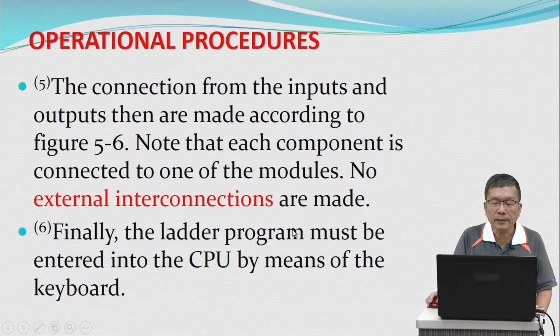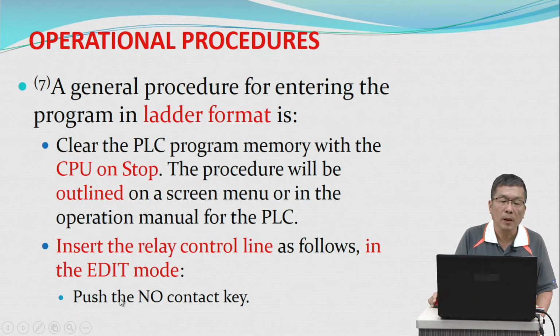Finally, the ladder diagram must be entered into the CPU by means of the keyboard. A general procedure for entering the program in ladder format is: clear the PLC program memory with the CPU on stop. The procedure will be outlined on a screen manual or in the operation manual for the PLC. Insert a relay control line as follows in the edit mode.